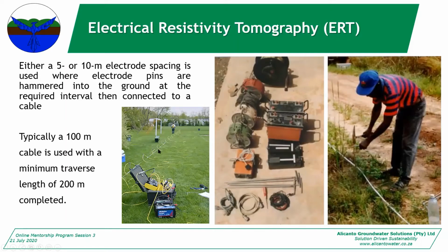So those are M and N. All that the control box does is, because the control box will know this is electrode 1, 2, 3, 4, etc., it will assign electrode 1 as M, and then electrode 2 is B, and then electrode -1 is N, and then electrode -2 is A.